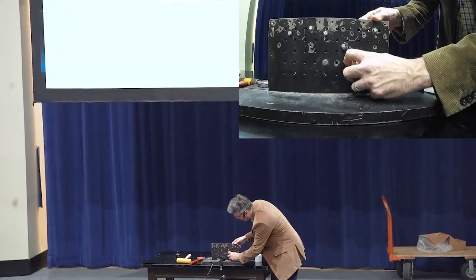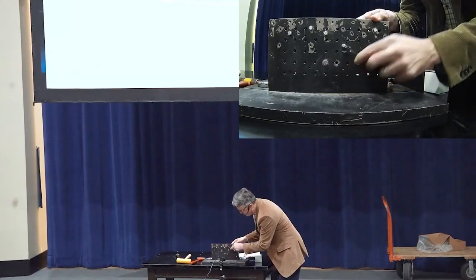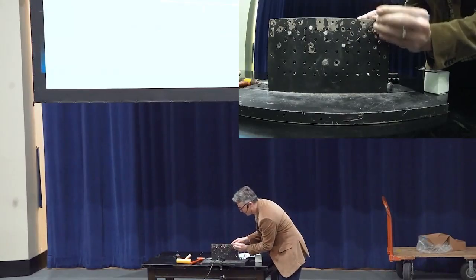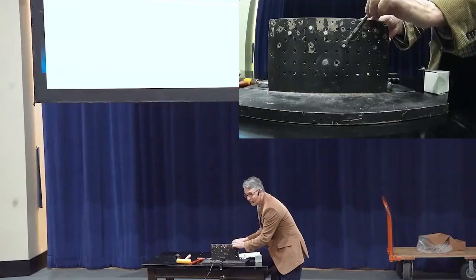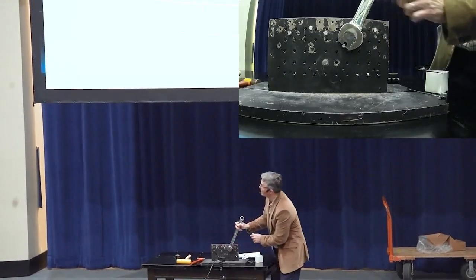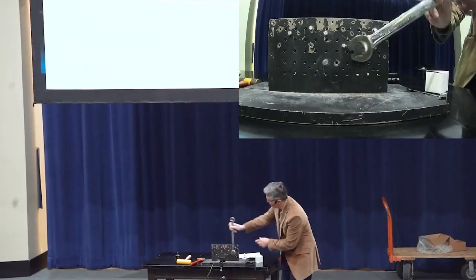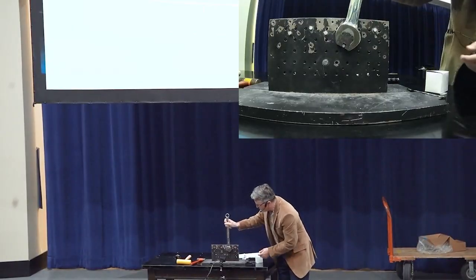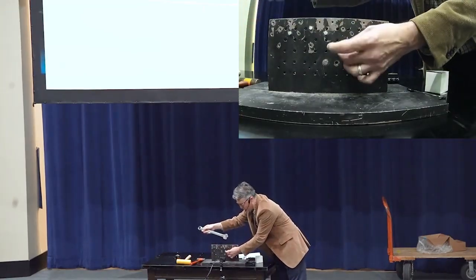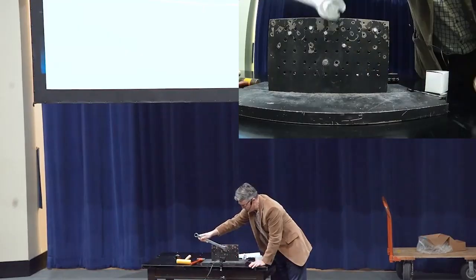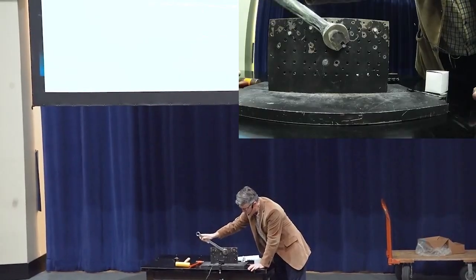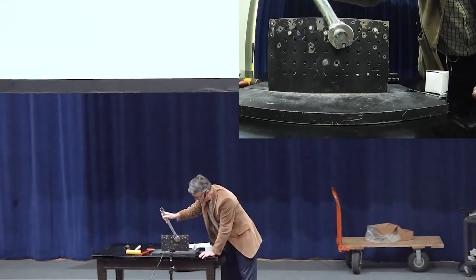Anyway, then we have all these little bolts, and I can screw in this bolt so tight. I don't know if you've ever overscrewed something where you can't loosen it. Well, it may be difficult to loosen, but if you're smart, you can get a bigger wrench. Pick out one like that. You can't really see it even in this, but I can apply the same exact force and loosen it very, very easily with a longer lever arm for the same bolt, because what matters to tighten or loosen this is the torque that you apply. So if you can only apply a certain amount of force, you can really increase that torque by increasing the lever arm.